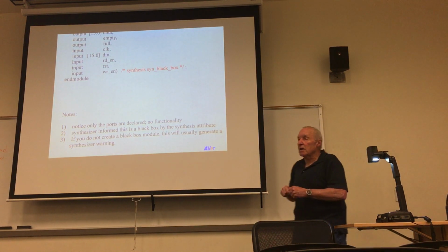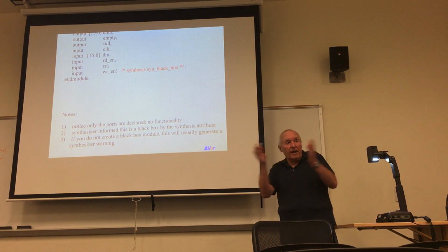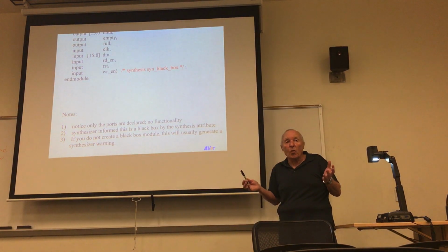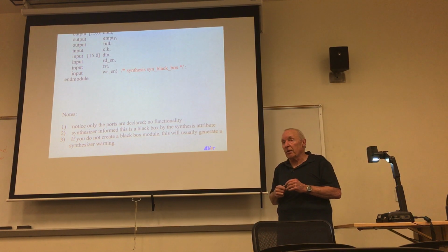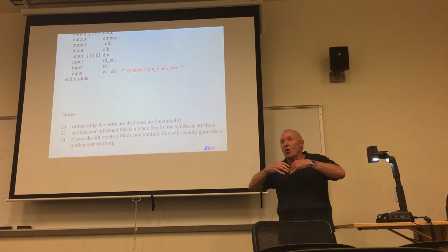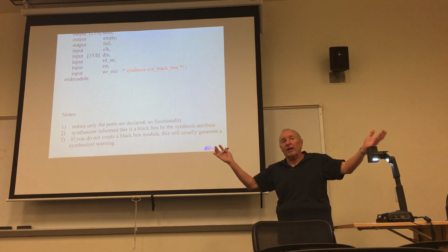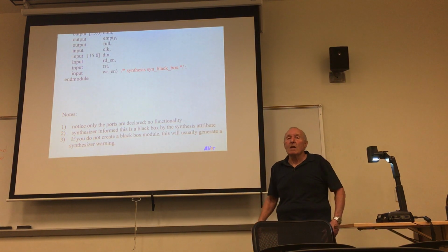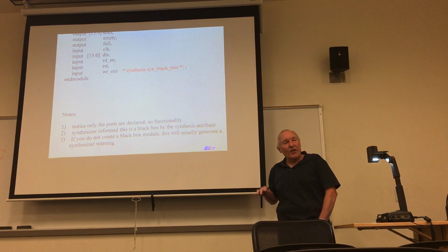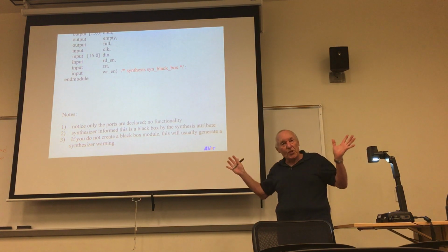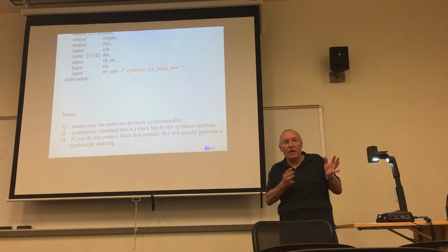If I tried to synthesize that code that you previously saw and I hadn't done this black box module, I'd get a synthesizer warning. Some synthesizers may actually generate an error. But the warning will usually say something to the effect of, well, I didn't have any information, so I'm just presuming it's a black box, and that's the way I'm going to implement it. Well, those warnings can be very irritating. That synthesis attribute purges all those warnings. You won't get them because you've actually defined a black box.